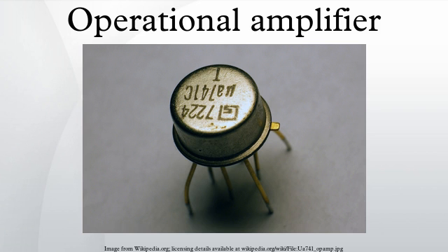Finite input impedances. The differential input impedance of the operational amplifier is defined as the impedance between its two inputs. The common mode input impedance is the impedance from each input to ground. MOSFET input operational amplifiers often have protection circuits that effectively short-circuit any input differences greater than a small threshold, so the input impedance can appear to be very low in some tests. However, as long as these operational amplifiers are used in a typical high-gain negative feedback application, these protection circuits will be inactive. The input bias and leakage currents described below are a more important design parameter for typical operational amplifier applications.